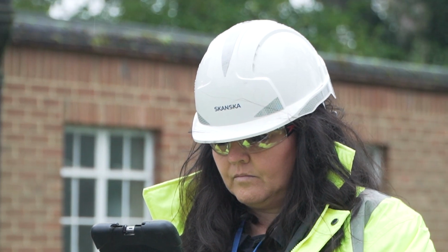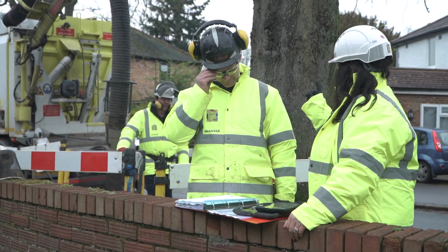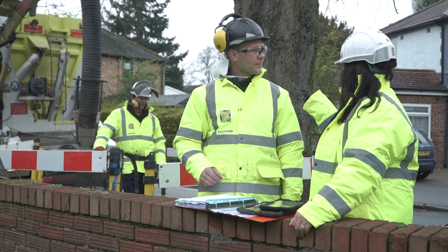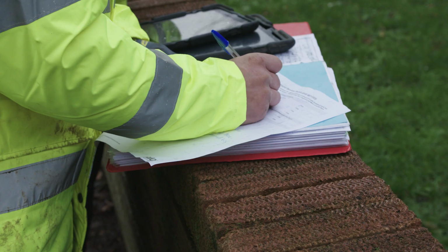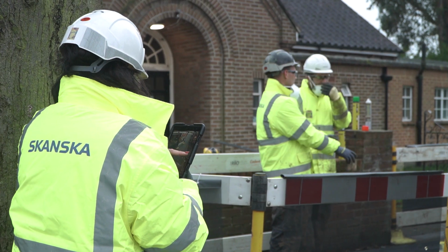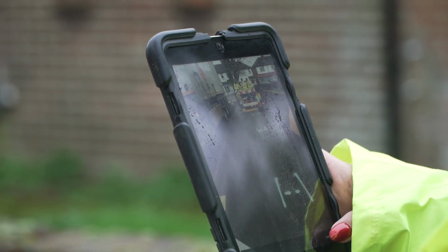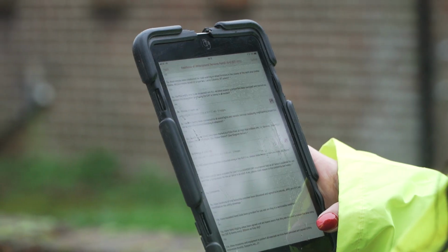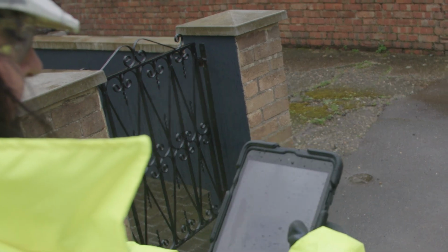and also on client requirements. The USAP will then issue, authorise and ensure the full briefing of the underground service avoidance permit to the working team. The details of all authorised permits are entered into the permit register. The USAP will monitor conditions of the permit during work activity, including identification of the surfaces in concrete or any other obstructions. Finally, the USAP will manage the closing out of permits upon completion of activity.